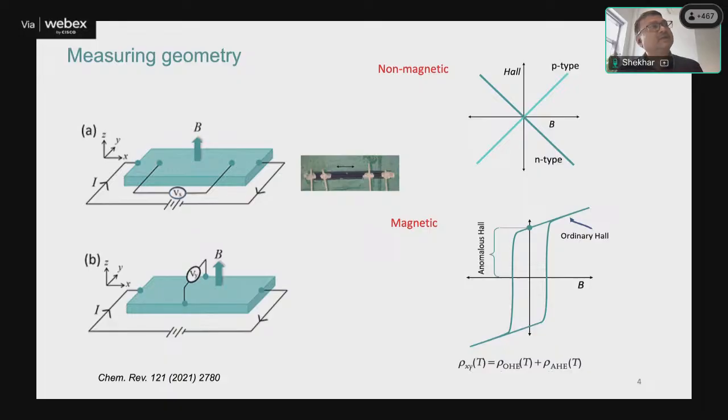but we need to calculate the geometry of the sample, where we have the length and the area of the cross section. These two are the voltage leads, and the outer ones are the current leads. We flow the current with the help of a source meter, then measure the voltage difference with a voltmeter, a nanovoltmeter. So this one is linear.